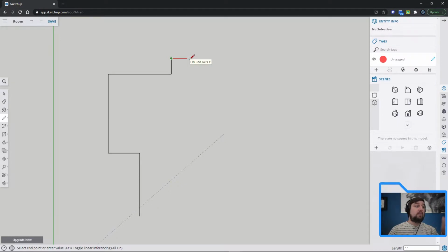All right, for the wall. I have a door in that other wall I just drew, and I'll show you how to make the opening for the door. But I'm just going to draw the opening for the closet right now since there's walls and stuff on the inside. So let's say this goes over 18 inches. Right, and then the thickness of the walls are all 4 inches. We're going to offset by 4, so I'm going to make this 4. I'm going to line this up over here. My closet is probably 2 feet deep, so that's 24 inches or 2 feet.